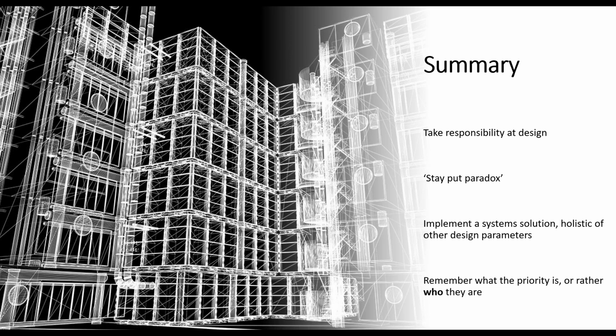So if we make those assumptions at design, if we're talking about these buildings that we are still engineering and designing to allow people to stay put in unmanaged residential scenarios, then through the application of a detailed design narrative using appropriate design fires, we can begin to think about the behaviour of our passive and active systems, such that, for example, we might just let our evacuation lifts run, so that someone requiring level access can call the lift and exit that building in a safe and dignified way, because they probably will be evacuating, depending on the design fire scenario you've chosen, because there's a dwelling fire, and it's their dwelling fire that they're shutting the door behind on.